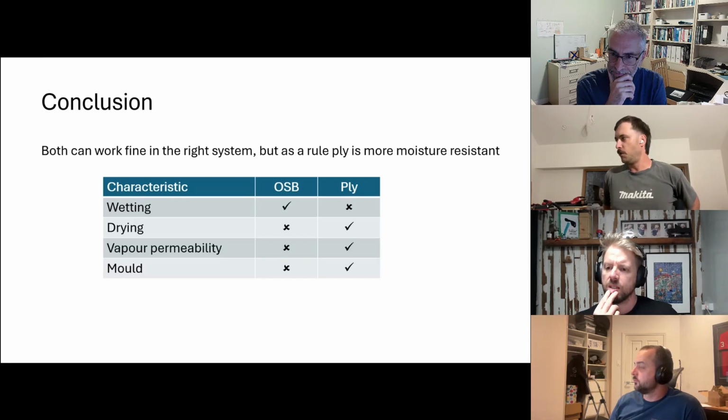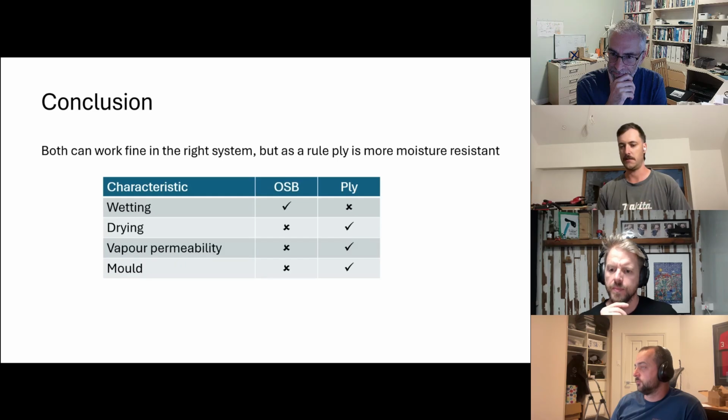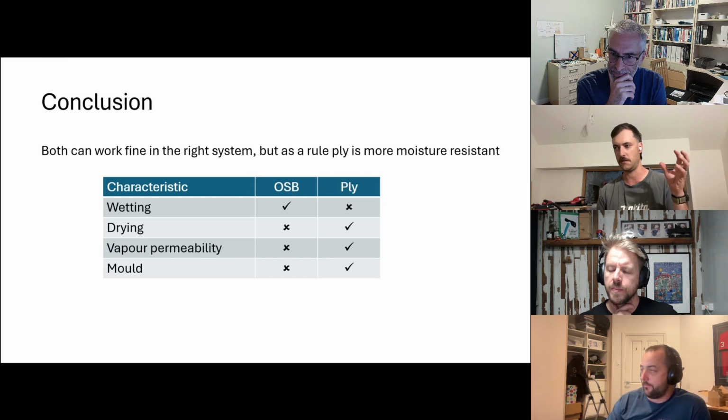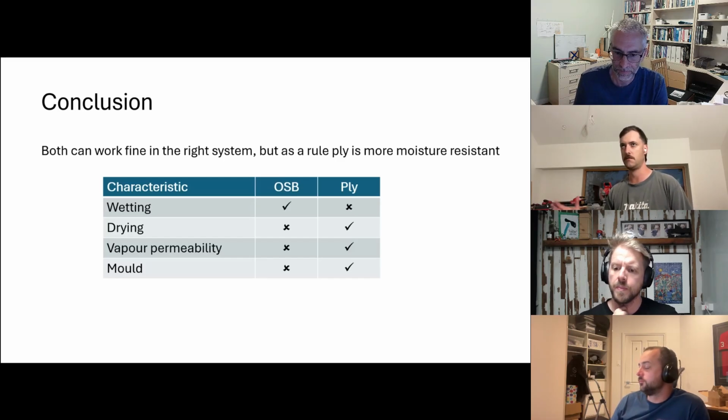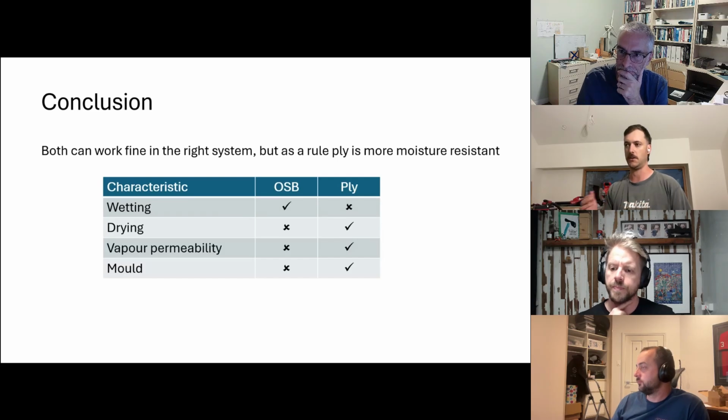So what we commonly see in parts of New South Wales, Victoria, South Australia, Tasmania, is inside the air molecule is fat with moisture molecules attached. As it goes through the insulation, it cools down and condensates at the dew point. But what happens in summer, when in the afternoon it's 30 degrees outside, you get the rain in the afternoon, the opposite happens, because you've got the aircon inside.